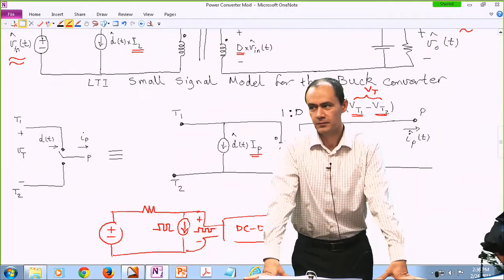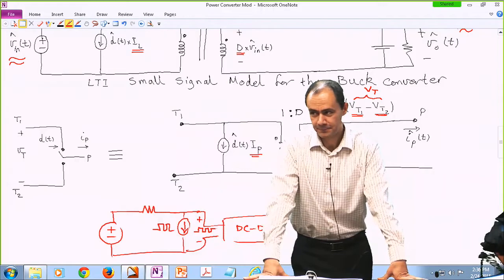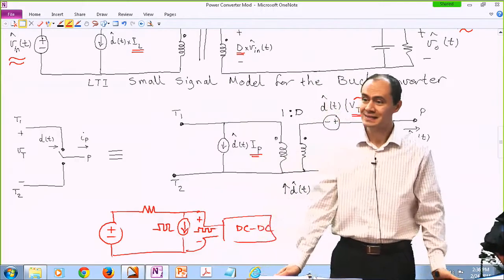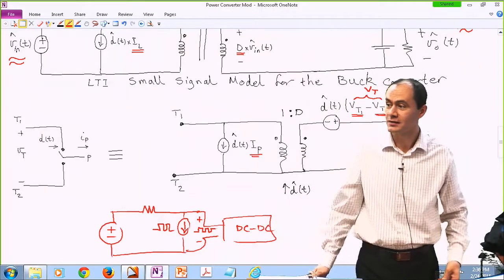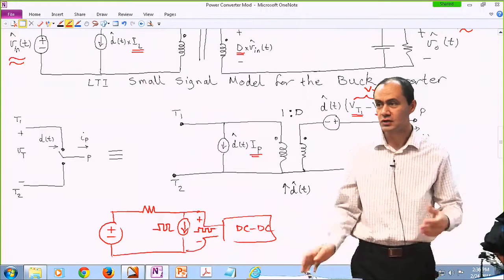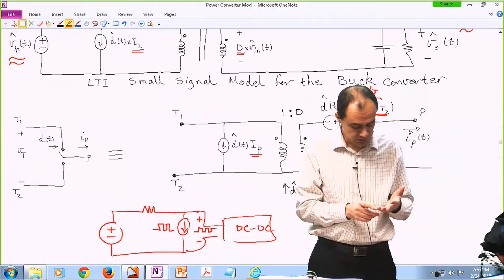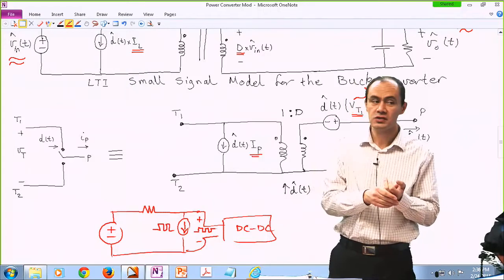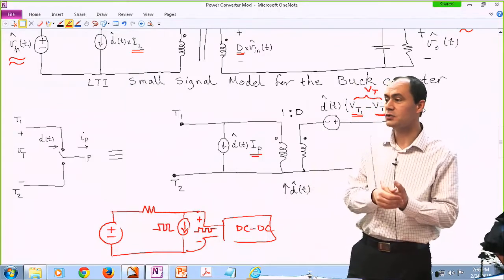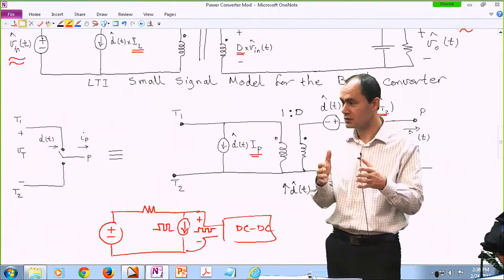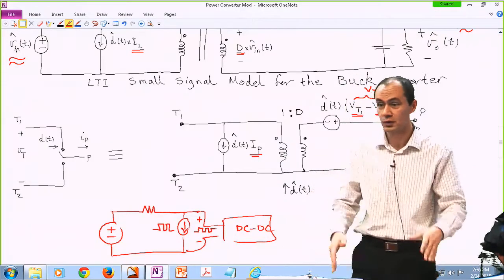So in the equation before, it doesn't make it non-linear when input voltage is multiplied with T. It is not something we can control, but it is still an input to the system. It's a disturbing input to the system. The inputs to the system, and we're going to see them in a few minutes, are variations in the input voltage, variations in the load current, and variations in the duty cycle. These are all three inputs to the system. The only one that we can control is the duty cycle. The rest are out of our control, but they are still inputs.